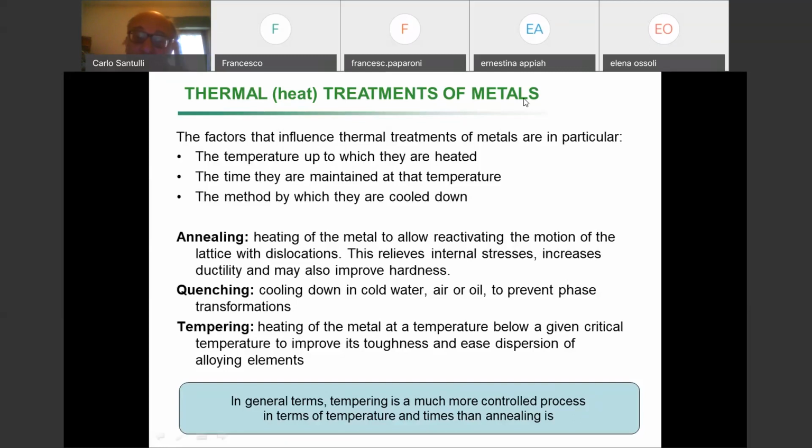If you add a second alloying element, which might have a very low melting temperature, for example zinc, you may get in trouble because your melting temperature goes really down. Of course, melting temperature depends on the relative amount of every alloying element, and then it behaves like a defect. In addition, the influence of temperature might be very different depending on the alloying elements you have.